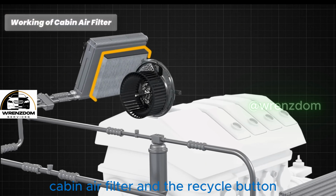When the recycle button is activated, the car's HVAC system stops the flow of air from outside and recirculates the air already inside the cabin. By recirculating the already cooled air, the AC system can cool the cabin more quickly and efficiently. In recirculation mode or fresh air mode, the air should be filtered. For this, an air filter is used.